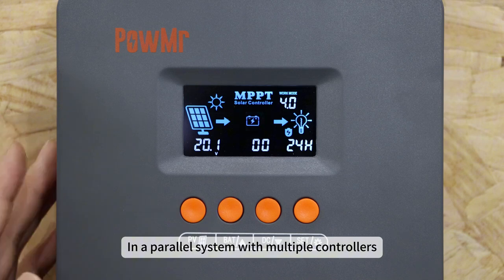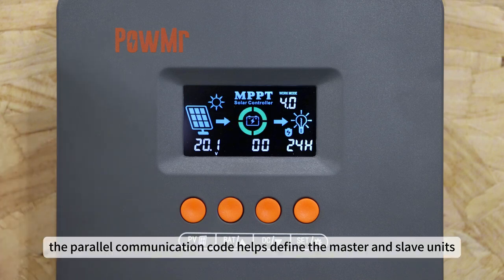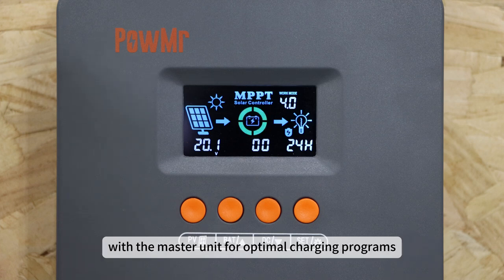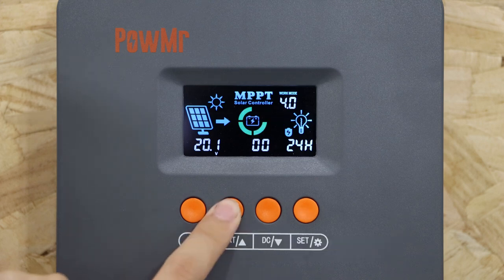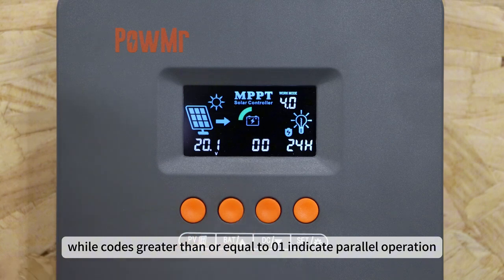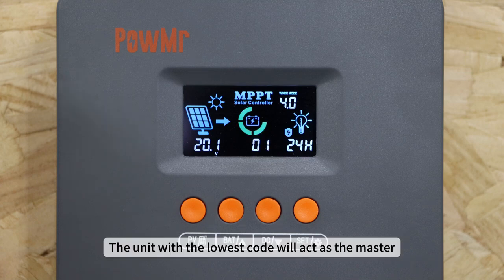In a parallel system with multiple controllers, the parallel communication code helps to define the master and slave units, ensuring that all slave units' charging programs are synchronized with the master unit for optimal charging. Code 00 represents single unit mode, while a code greater than or equal to 01 indicates parallel operation. The unit with the lowest code will act as the master.